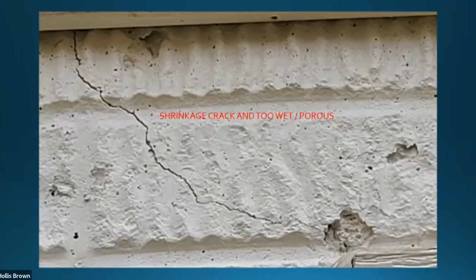Well, I'll give you my opinion, and this is going to be against the engineer. The engineer's thinking strength, but like I said, a concrete foundation for a house could probably support 50 houses. The PSI rating is off the chart. You don't have to worry about it from the standpoint of strength or settlement. It's a matter of any moisture penetration. And the flexible sealant will move as it continues to crack, where the epoxy is just going to fail. Again, you're just going to develop a crack next to the old crack.